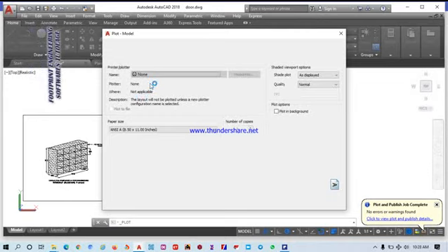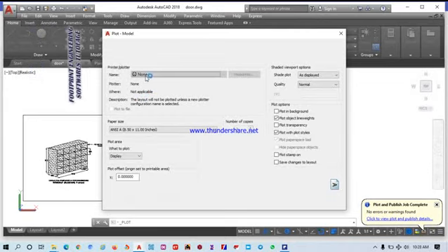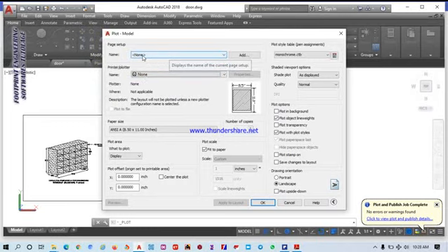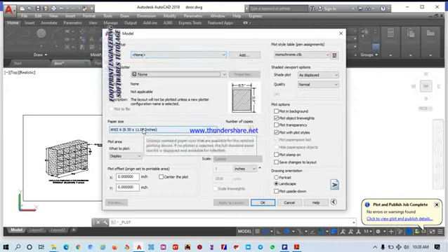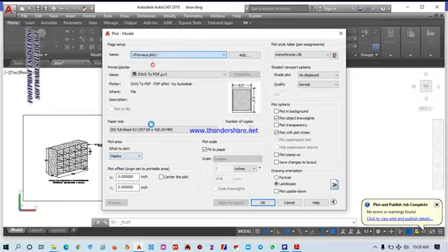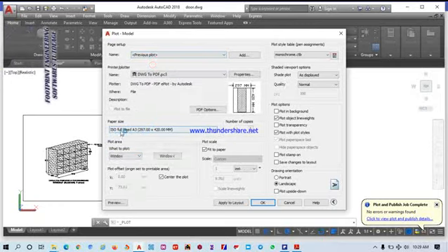you see the page. Like I said, you don't have anything to do with this name. The only time you need this name is maybe you've plotted a drawing and you want to use the same setup for the next drawing that you want to print, or you want to change to PDF, maybe like the paper size. This window, you don't want to go there again, just go to previous. Once you go to previous, can you see all those settings are there, all those windows? You don't have to do them again.